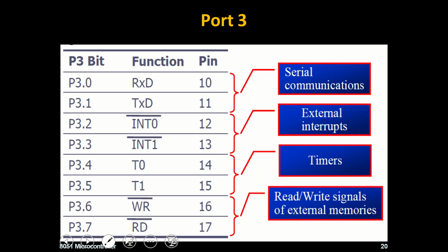Next, port 3. Port 3 has some special features. Some pins are used for serial communications, some pins are used for external interrupts, some pins are used for timers, and some pins are used for read and write signals of the external memories we have connected. So the functions of each pin are tabulated here.